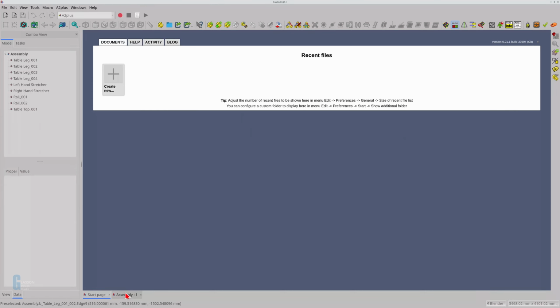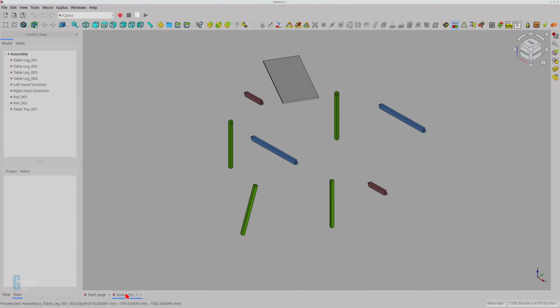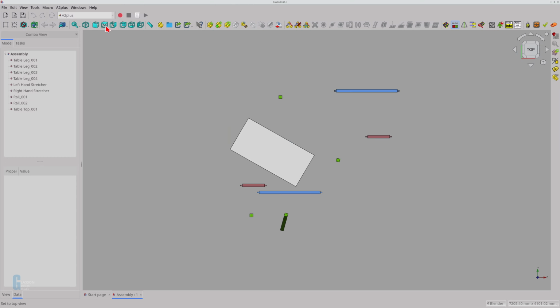First, I'll show you how to use the plane coincident constraint. This constraint makes the 2 planes coincident to each other. I use this constraint most in my work because it closely matches my intended application in woodworking. That is, making 2 faces coincident so they can be glued together. I have placed the parts in random locations to help show the effect of the plane coincident constraint. You'll need to place 3 plane coincident constraints for each joint in the table.